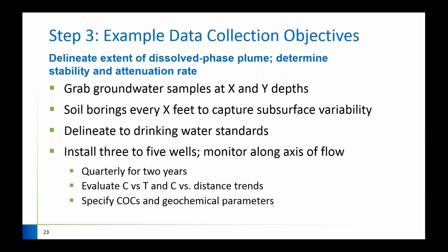Back to our dry cleaner, you can imagine coming up with objectives that say, we're going to delineate the extent of the dissolved phase plume. We're also going to look at attenuation and degradation from those remedies. To do that, we're going to collect groundwater samples at specific depths. We're going to collect soil borings at specific depths. We're going to keep delineating, stepping out until we get to standards. And then we're going to install wells to monitor the remedy.